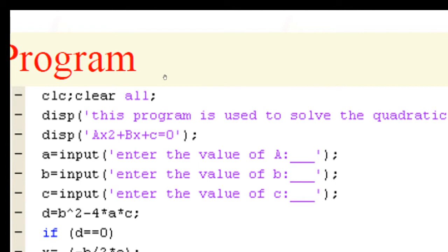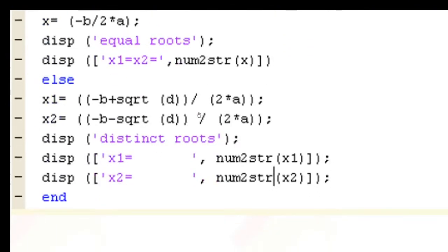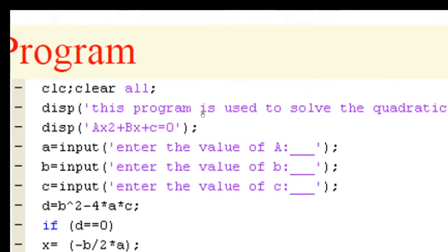Participants, since we are having more commands here, better you store the program in an m file. If you have 2 or 3 or 4 commands, you can enter them in the command prompt itself. Whenever you are using loops, or you have a larger set of commands, better you store it in an m file and run it. At the end, if you want, I will show some sample programs for the m file and how to run it. Okay, don't bother about this one.